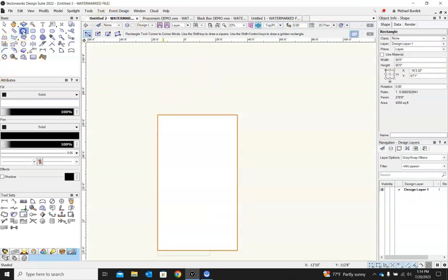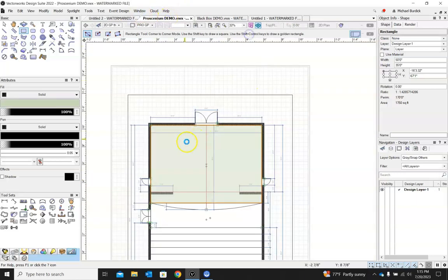So I'll come over here and, foot by, like I said, it was 35. Tab, and because I'm drawing down from where my first click was, it's going to be a negative, so it'll be 50 foot auto-filled correctly because it locked in, and then negative 35 foot. So that is good to go.